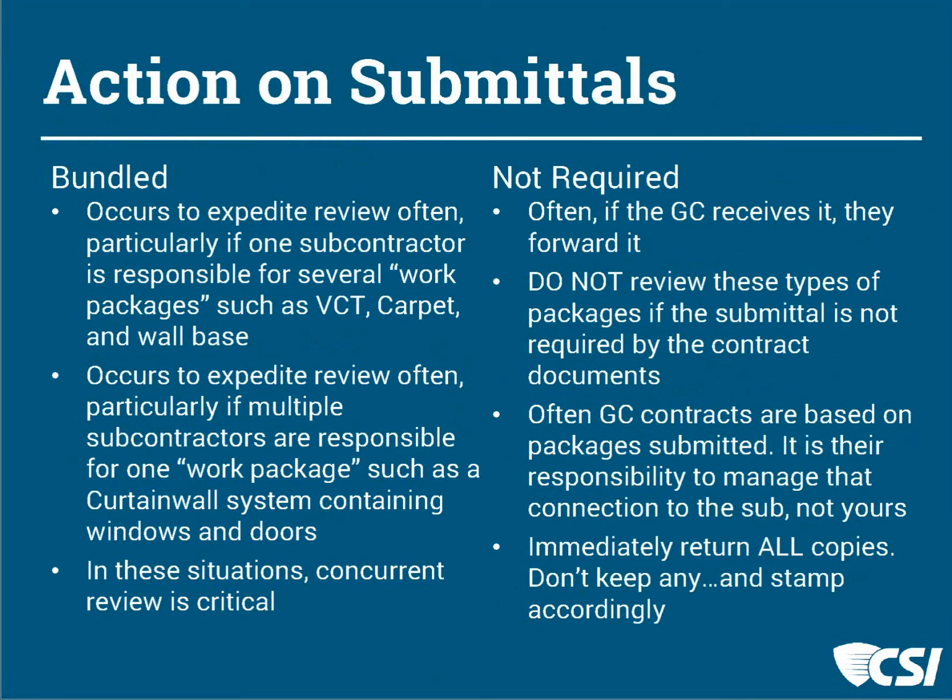Doug, who presents these along with me, and other attorneys have said, when you do that, you return every single copy and do not retain any copies in your office. If you receive a submittal that's not required by your contract documents, stamp it, no action taken, and send them all back. Because you don't want a copy of something that you don't require related to that contract in your project files. That's an action that might generate a lot of hard feelings, but it's important to do.